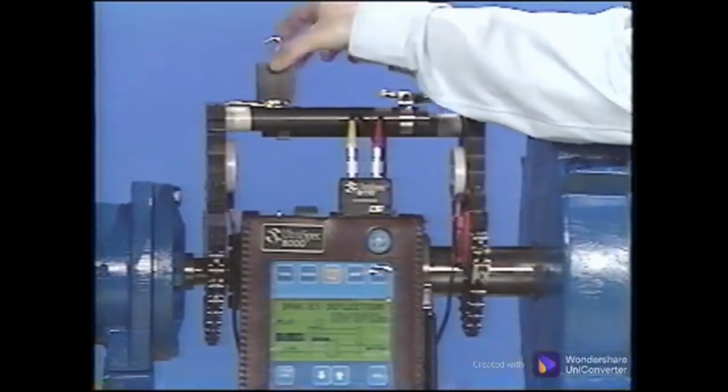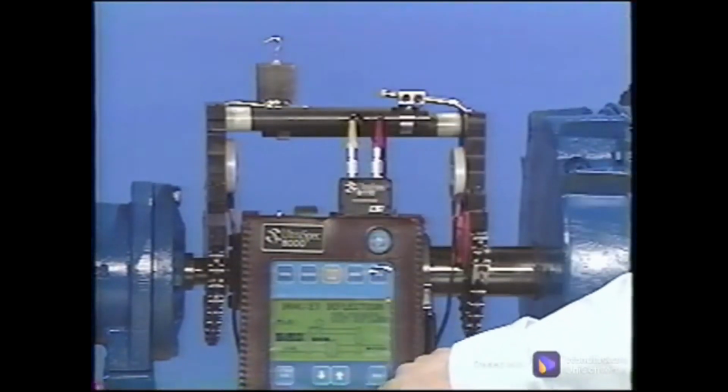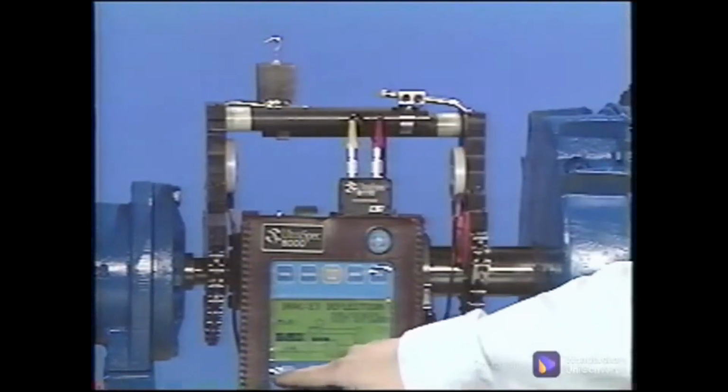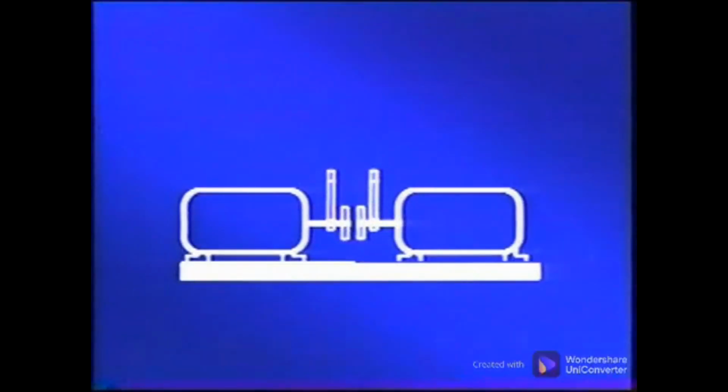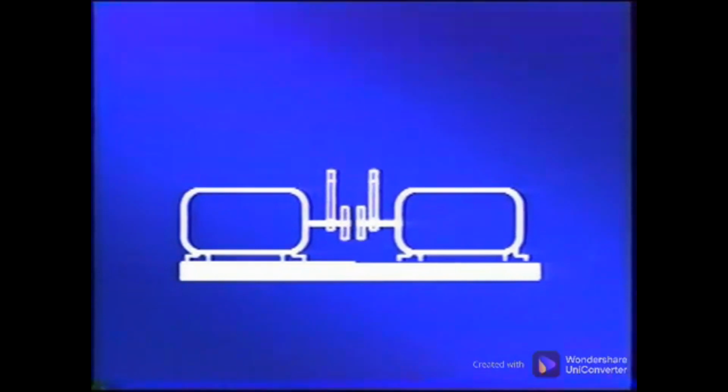It measures bar sag with the heads and bars installed, therefore eliminating that pre-alignment check. It reduces error from reading dials by digitally measuring the movement and transferring it to the alignment analyzer, which calculates the moves. If the machine is not coupled, position it axially before making any measurements.